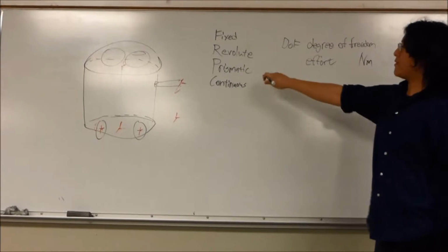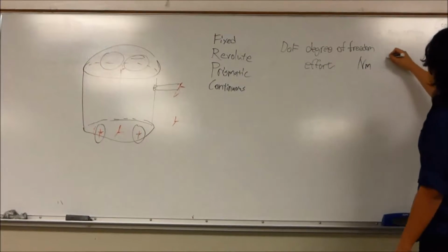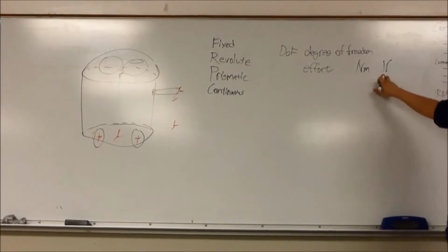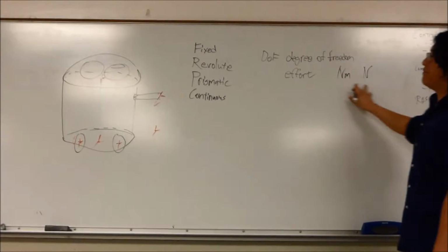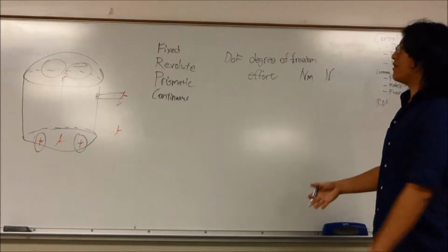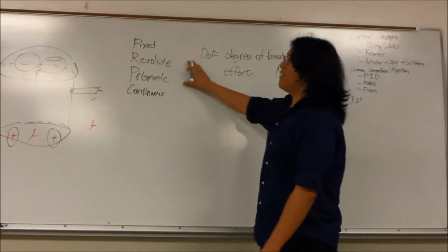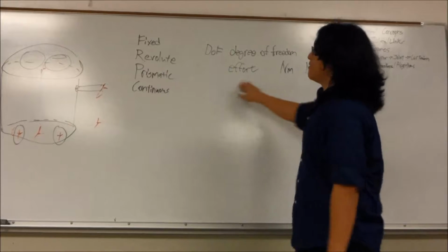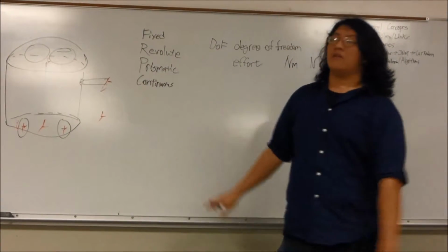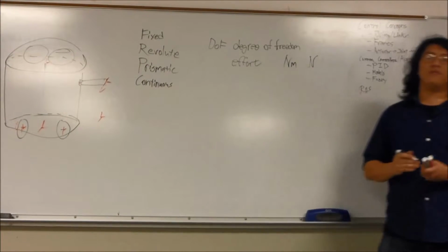Whereas if you have a prismatic joint, you talk about in terms of your force, which is in the unit newtons. Although in a robotic system, you commonly don't want to have to consider the two cases separately, and so you refer to either of these units as your effort, depending on what kind of joint you have.